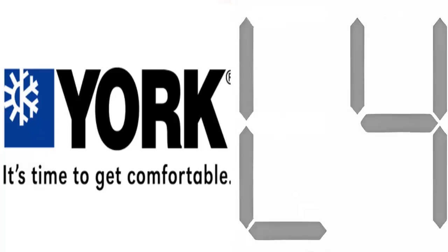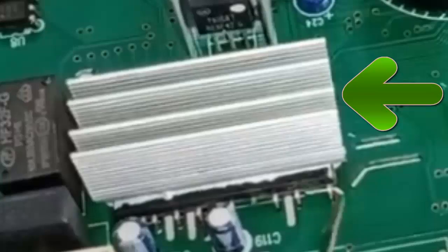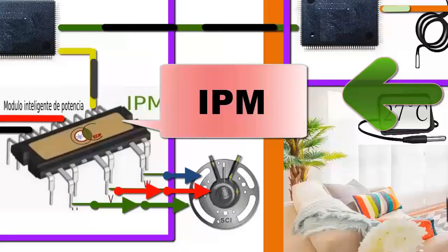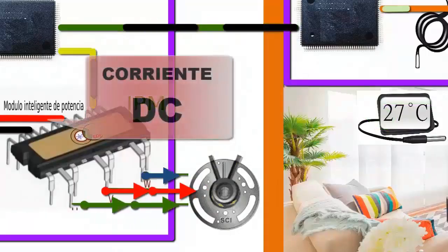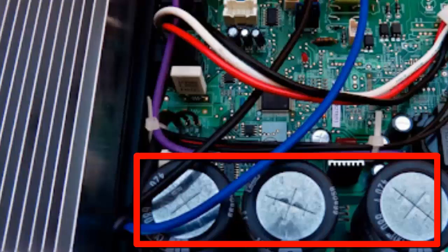Code P0 and code L4 are generated when the protection of the inverter module, known as IPM, is activated. These codes usually appear when the heat sink of the IPM module is loose and does not make perfect contact, or when there are problems with the insulating paste or gel, or the screw that secures the heat sink to